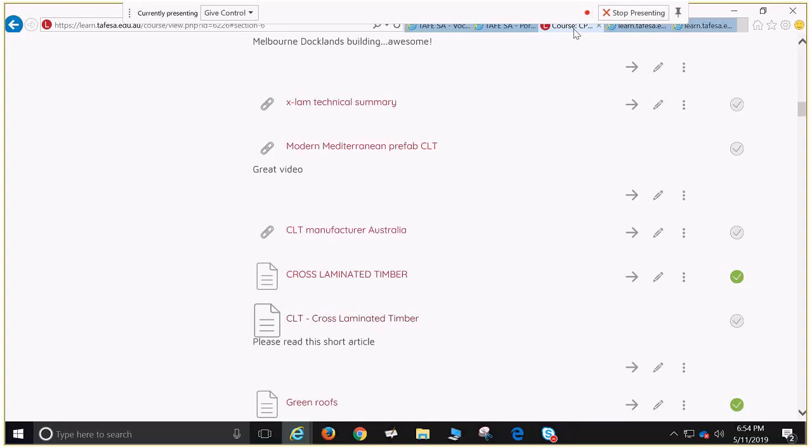So we typically don't use steel in large enough volumes to contribute significantly to thermal mass, but if we were to have a cubic metre of steel in the room and heat that up, it would take in a lot of that heat. We can put a lot of kilojoules into that cubic metre of steel, as opposed to a cubic metre of Pinus radiata. Because steel is highly conductive, it will give off that heat much quicker than, let's say, a cubic metre of rammed earth or a cubic metre of concrete.